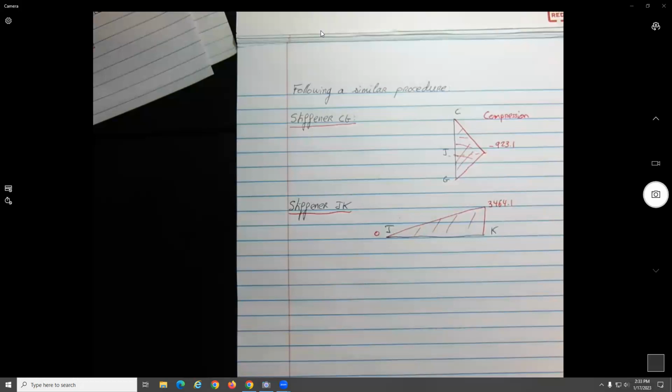You look at the final element, it is giving you 9,943.1. The reason is that it's taking the average between the tip and the next element, which is over here. So if you look at this one, it's giving you the average between this point and the next element on the mesh, that will be right here, no? But you see, basically they follow the same behavior. Let's say we take this one. Show full model. Let's take maybe the element at the tip.